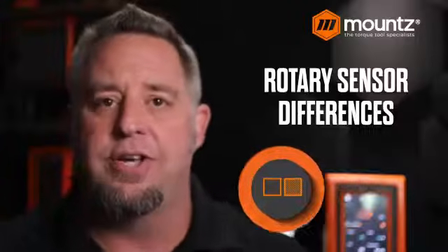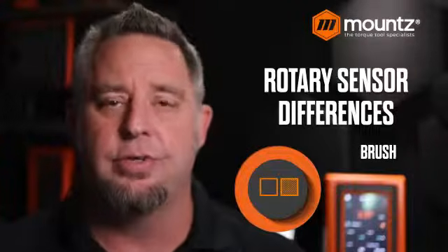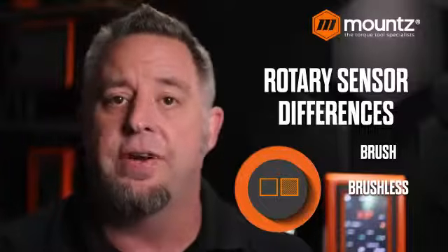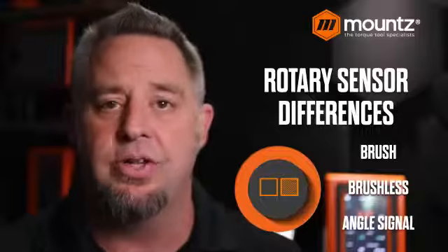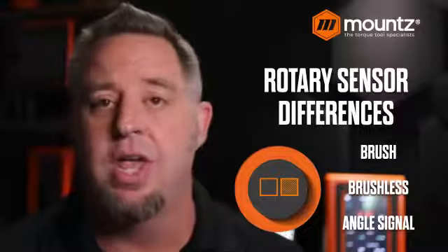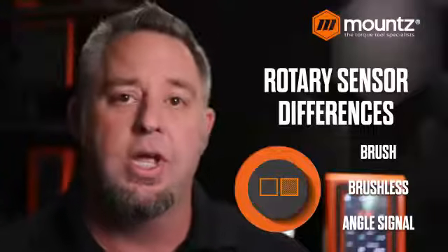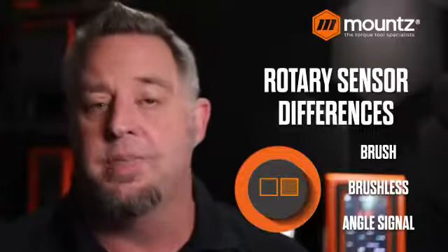There are a few different styles of rotary style transducers. There are brush style transducers. These would be used again for R&D or possible torque verification. We do have brushless models. These would be helpful for use where a sensor is going to be part of a permanent piece of the assembly process. So that torque sensor is going to always be present, capturing readings of very critical joint assemblies. So we would use a brushless style transducer.